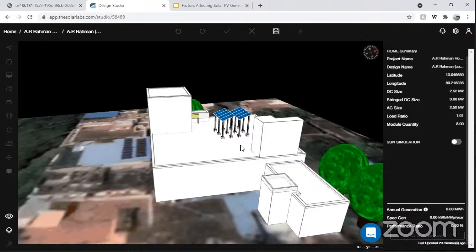So if my current value or my DC values shoot above the recommended value, it will just trip and stop the current right there. Similarly, we have ACDBs wherein we will be transferring that AC current from my inverter to my appliances. It will be in between so that it can protect our other devices.